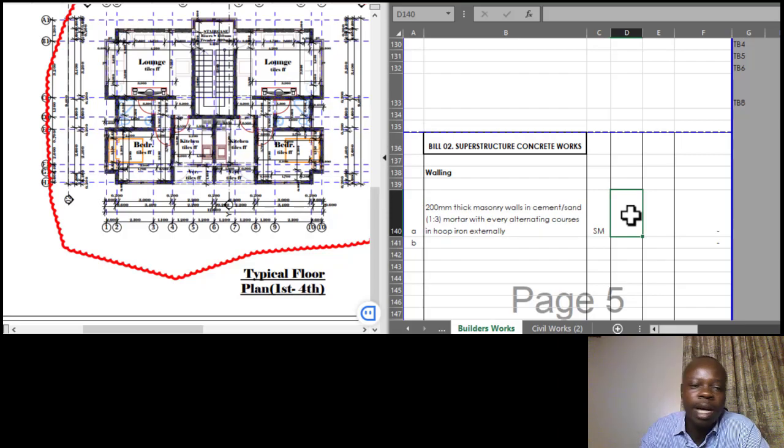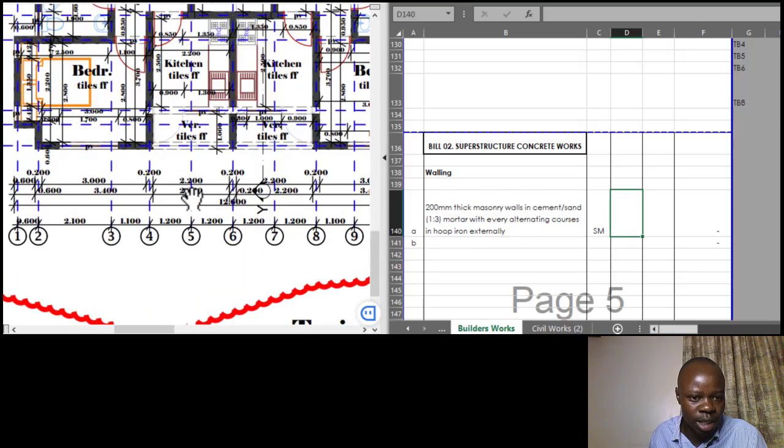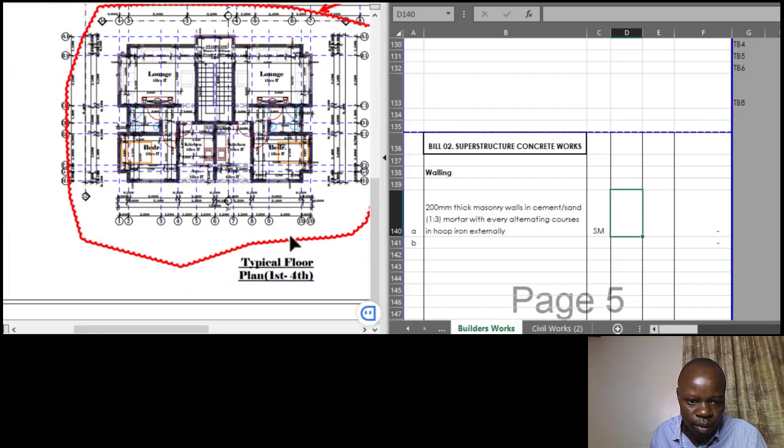All right, so regardless of the shape, from my previous explanation when I was finding the center line for some of the plans that we've worked on previously, you find that regardless of the shape, you can always refer to this as a perfect rectangle, and then you do adjustments for the recesses and also the extensions. When you do that, it becomes easier to achieve your area or your center line without trouble. So what I'm saying is, for instance, looking at this, we are doing our example using what we call a typical floor plan, which is replicated in different floors or in numerous floors.